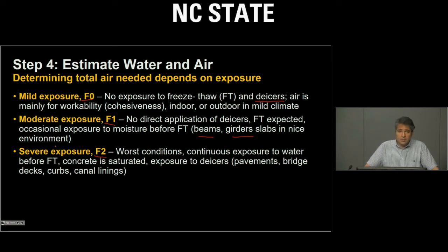Severe exposure is the worst type of exposure, that is continuous exposure to water before freeze and thaw. Bridge decks are examples of this. Pavements are examples of this. Concrete can be saturated in this particular case because of a lot of rain and water sitting at the surface of the concrete, and exposure to de-icers is expected. So really, these are the definitions of the 3 types of exposure that we have.